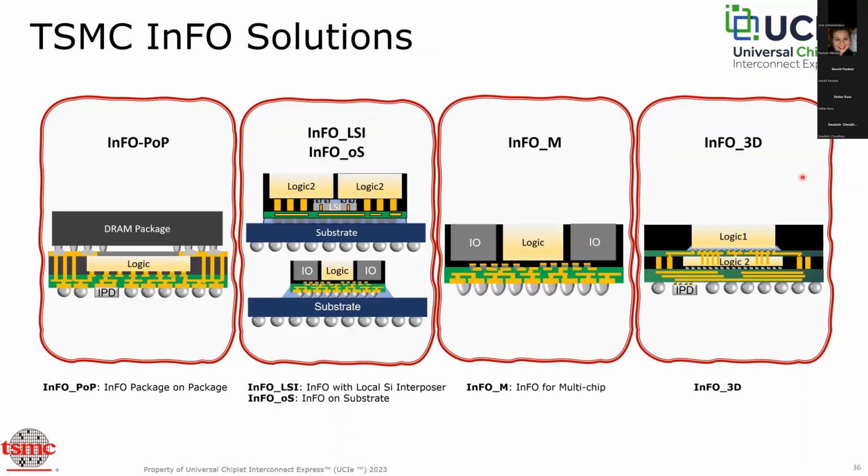The integrated fan-out technology is another platform. It has been in mass production since 2016 and initially was driven by cost-effective mobile applications. The InFO-PoP was the first 3D fan-out packaging solution to integrate the SoC with memory packages using 5 micron pitch copper RDL.